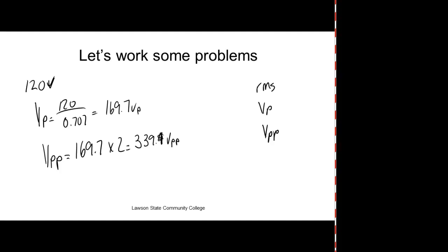And what are the odds of it being exactly 120 volts? Slim to none. The voltage can range 120 volts plus or minus 10%. So what you get at your house might not necessarily be 120 volts, right? You understand that? So normally I say about 340 volts peak to peak, and that's what my scope would measure. We'll look at that later on to see how our scope would measure that much voltage. And it will. We'll look at Alabama Power.